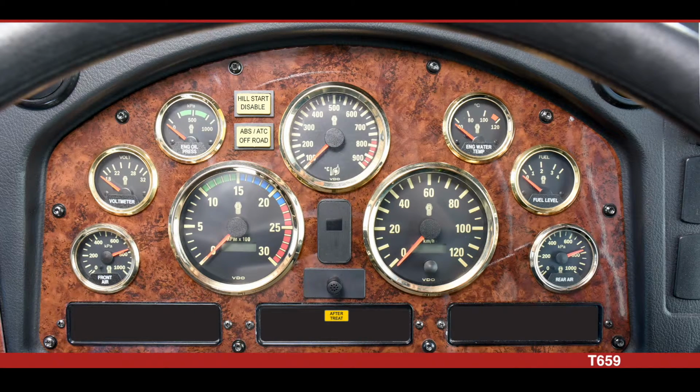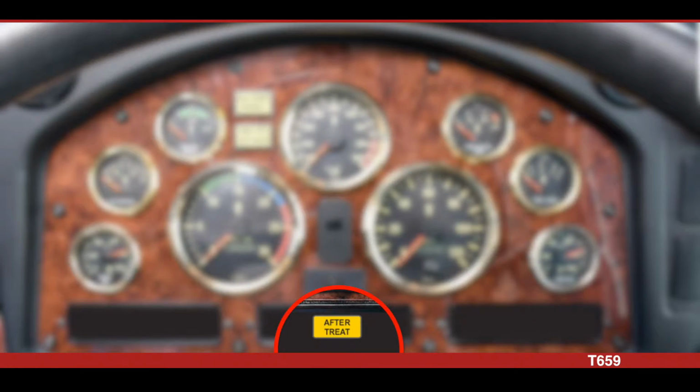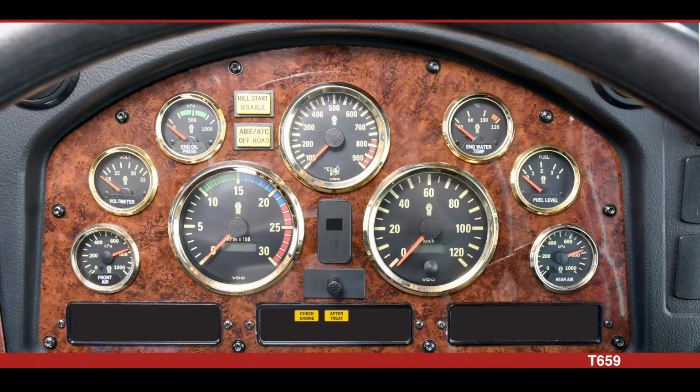The after treatment light will illuminate when the engine detects that the DEF quality is below acceptable levels. The after treatment warning light will flash, the check engine light will come on and the engine will be derated. If the engine detects the DEF quantity is below the acceptable level of 12%, the after treatment warning light will flash. When the level is below 6%, the check engine light will come on and the engine will be derated.